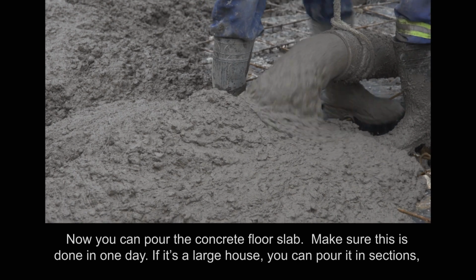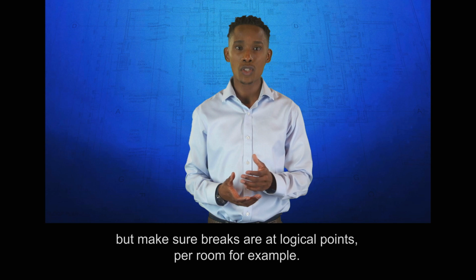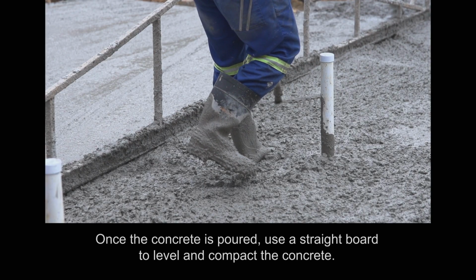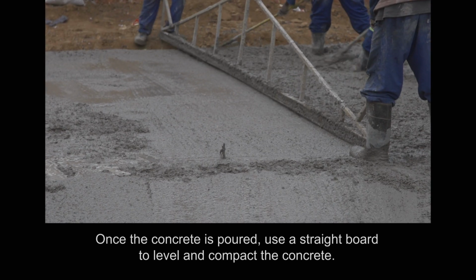Make sure this is done in one day. If it's a large house, you can pour it in sections, but make sure breaks are at logical points, per room for example. Once the concrete is poured, use a straight board to level and compact the concrete.